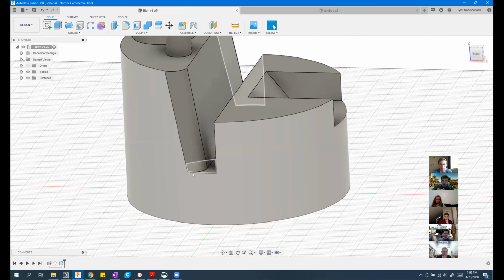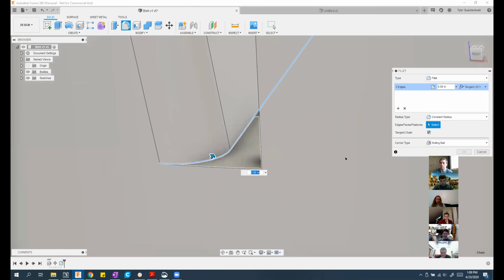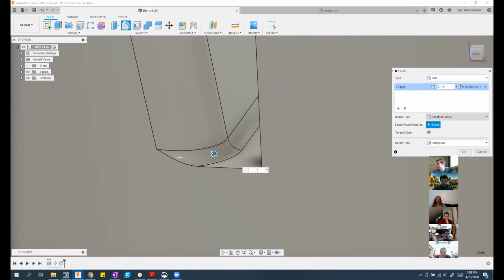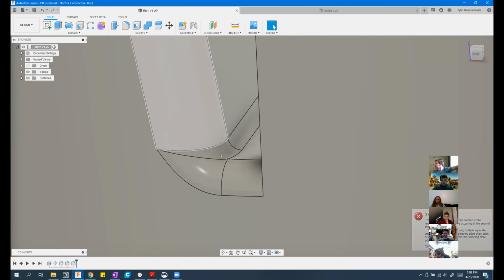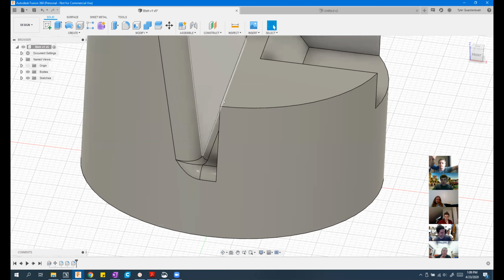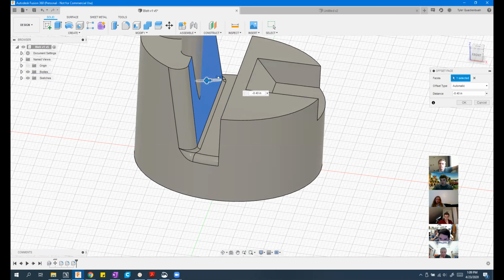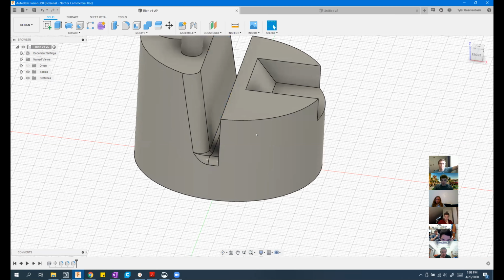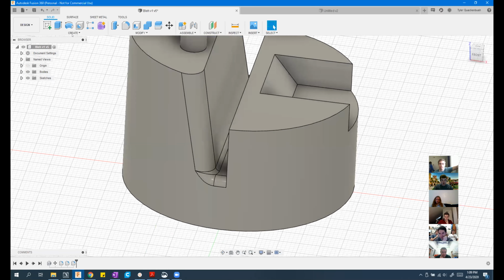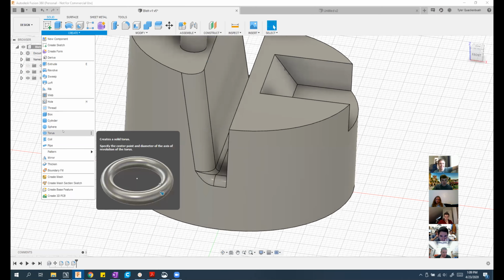I don't have anything that's broken here, but let's say this corner right here was super mega broke. And we've got like a mess of fillets right here. And we've just got some weird features right here, and we can't edit. Like, let's say we want to pull this face back for some reason, or just whatever we want to do. And I try to pull that back and everything breaks. There's a method you can use called the wound heal method. So basically what you want to do is you want to take your part and you want to break it, and then you want to fix it.